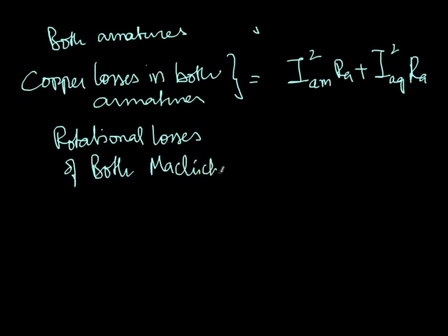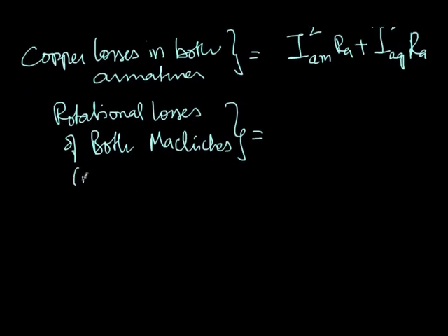So, what does the rotational loss include? It includes the iron loss, plus friction, plus windage losses, plus stray losses.